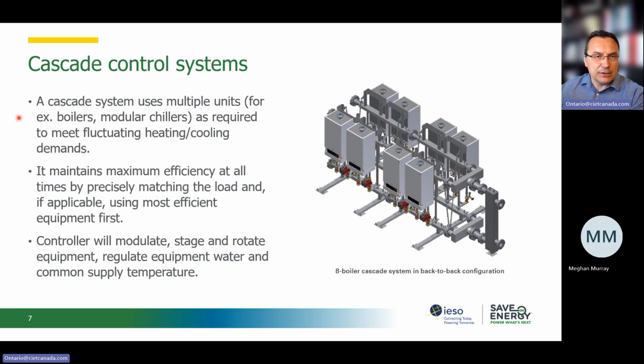At part load conditions, in shoulder months, we need less heating. We don't need to operate all 8 boilers at very low load factor, which results in an inefficient operation of the boiler, but we can select to operate those boilers that operate at the maximum efficiency point on their performance curve as provided by the manufacturers.